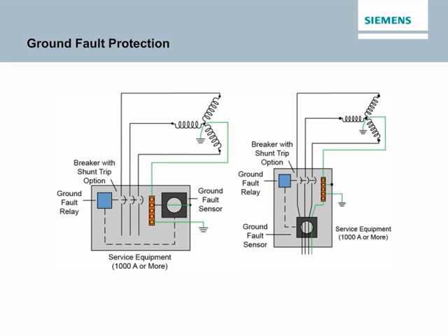Keep in mind that ground fault equipment protection must open a circuit when ground fault current reaches 30 milliamps. In contrast, ground fault circuit interrupters designed to provide life protection must open a circuit at 5 milliamps, plus or minus 1 milliamp. When ground fault protection is incorporated into a panel board, it is generally through the use of circuit breakers with ground fault protection.